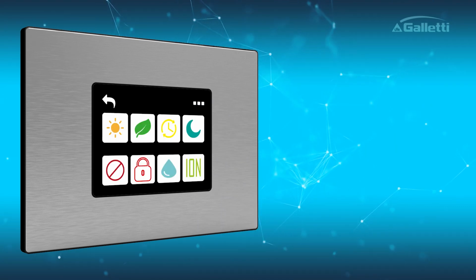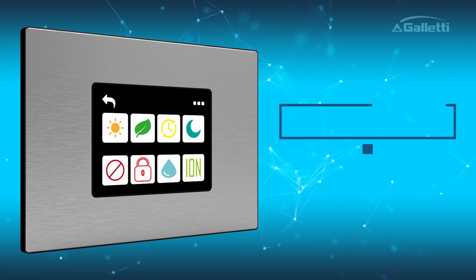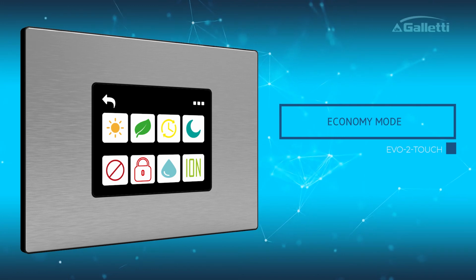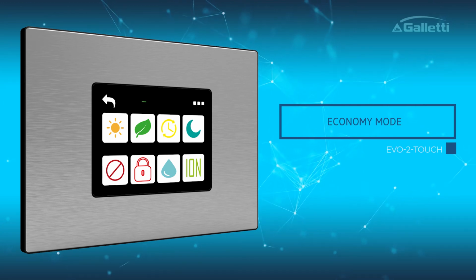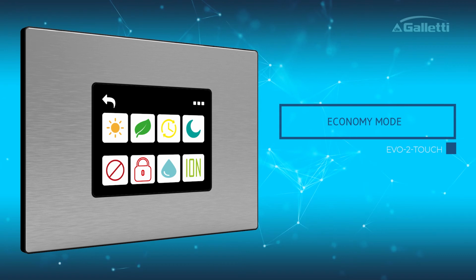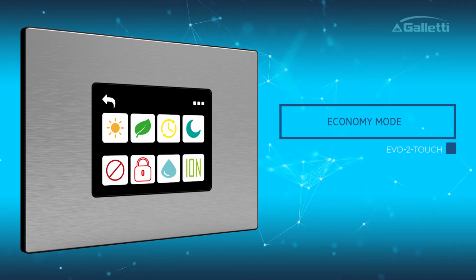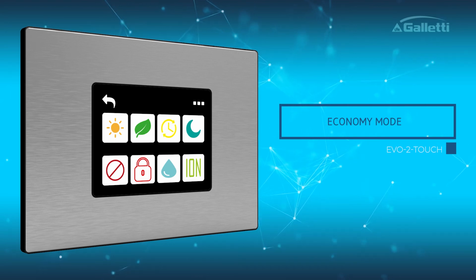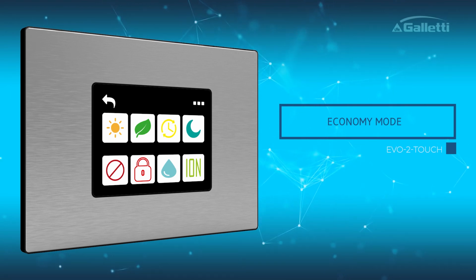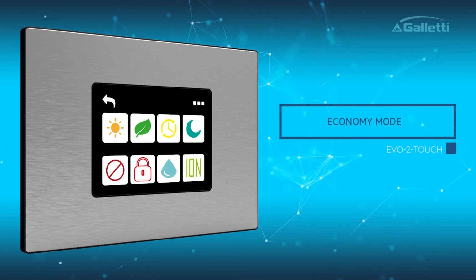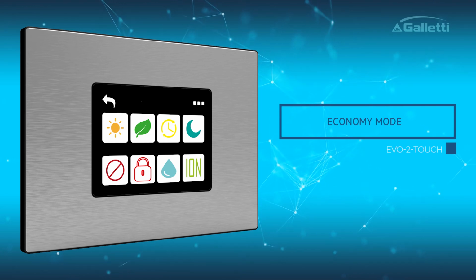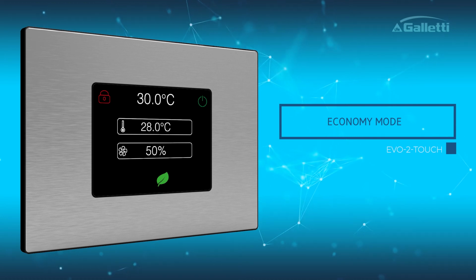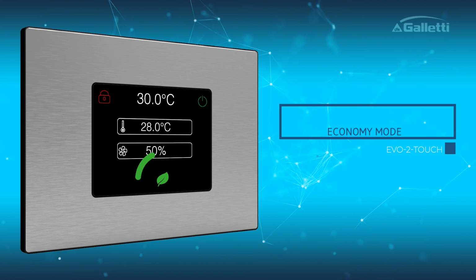To reduce energy consumption and noise levels of the unit as much as possible, the economy function has been incorporated into the controller. When this condition is set, the temperature set point is corrected with an offset of 2.5 degrees centigrade, and the speed is forced to the minimum allowed value. The economy function is activated by clicking on the leaf icon. The presence of the leaf icon at the bottom of the screen confirms that the unit is operating in this mode.